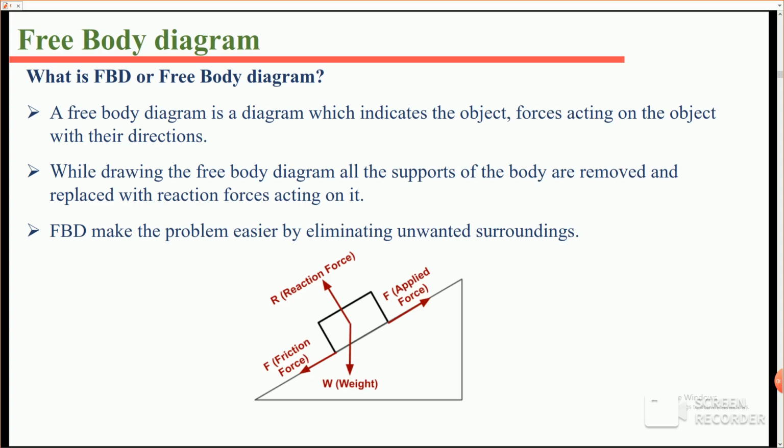When drawing an FBD, we remove all the supports or contacts and replace them with their corresponding reaction forces. This helps us focus only on the forces acting on the particular object. By using a free body diagram, complex engineering problems become much easier to understand and solve.